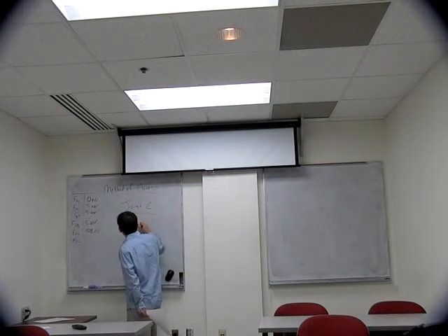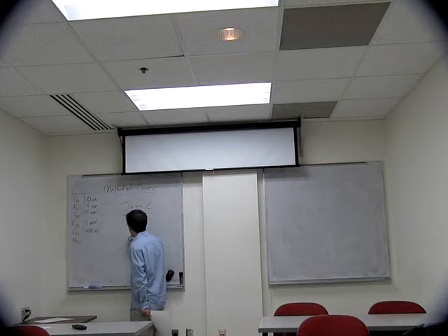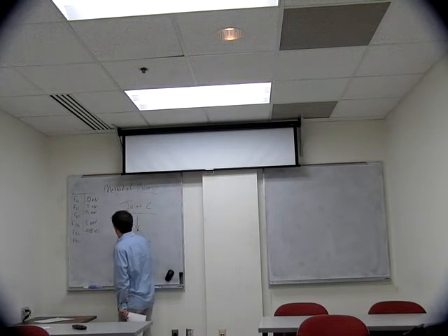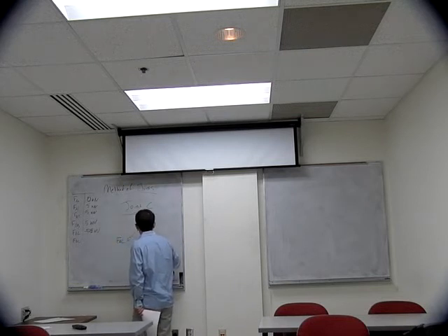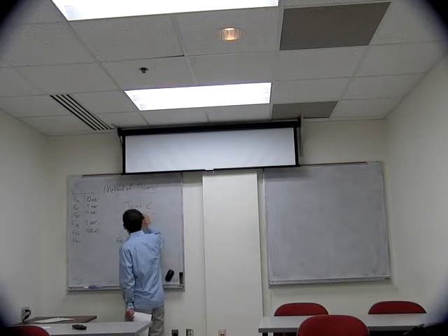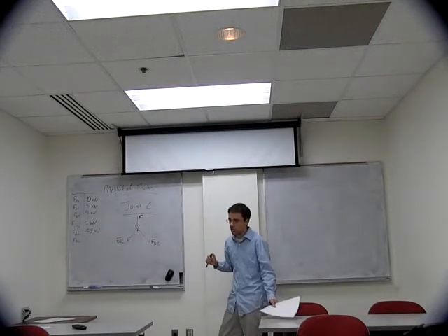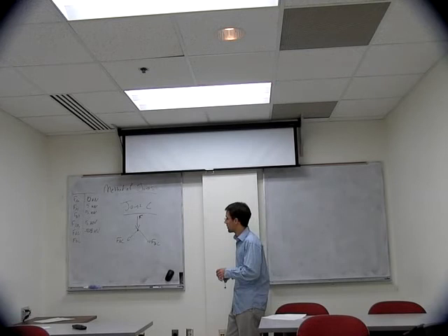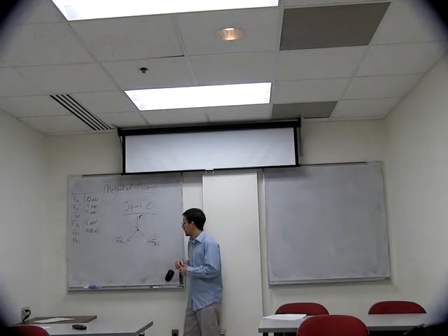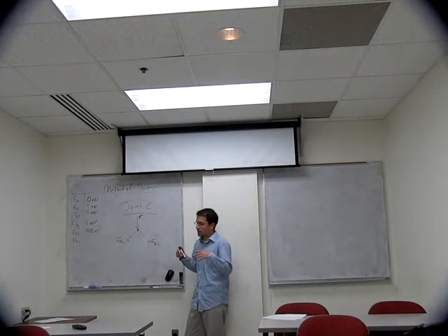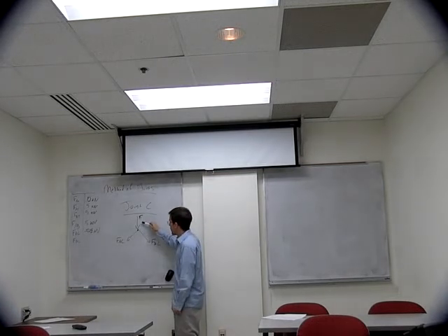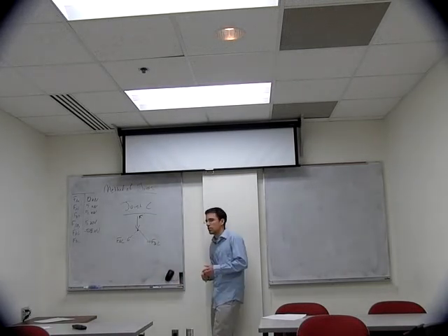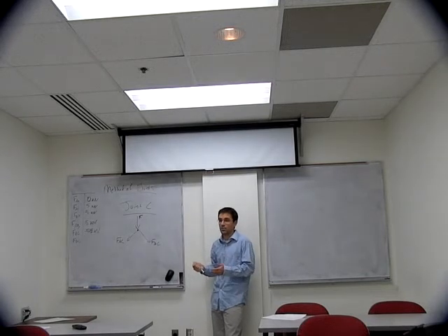So joint C, remember we had our applied force, and then we had our two member forces. So we have FAC and FBC. These are our applied force. And we noticed that one of the initial assumptions that we made, that the beams were in tension, was wrong just by looking at this free body diagram. We know that the system is going to have no net force, but if we look at all of these forces, all of the forces are in the downward direction. So we know that our summation can't be 0.